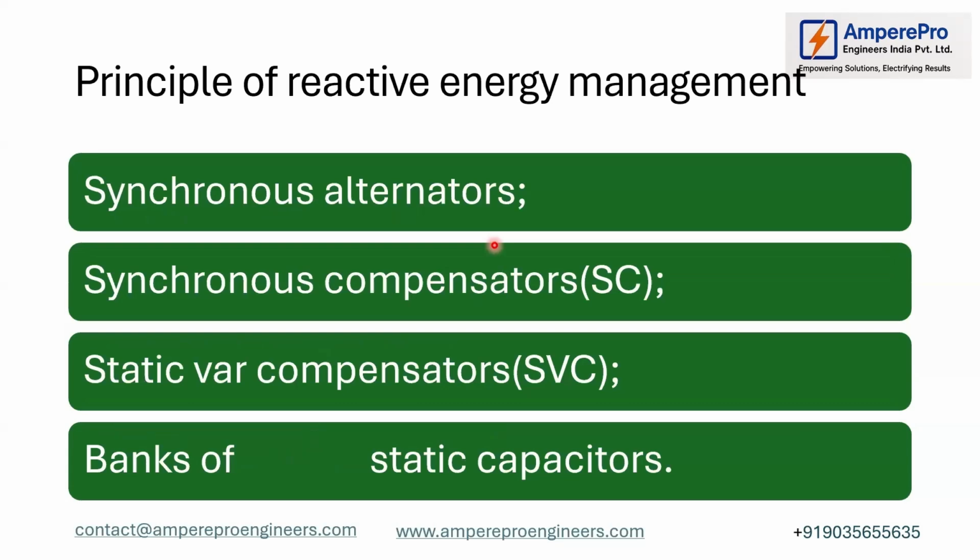Okay, so there are different ways of managing reactive power. One is synchronous alternators, second is synchronous compensators, third is static VAR compensators, and fourth is static capacitors.